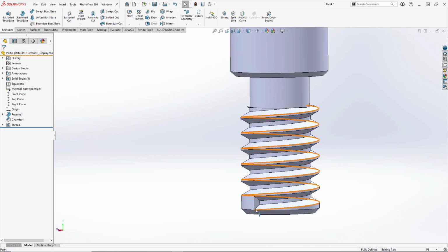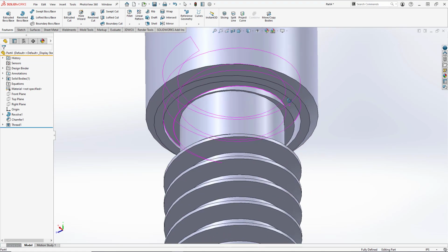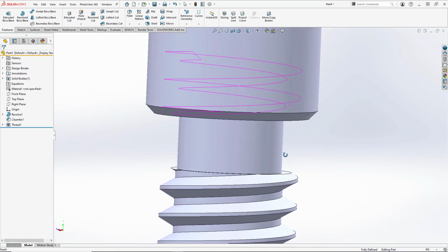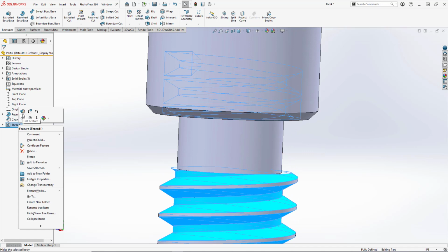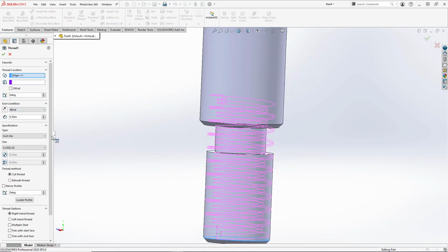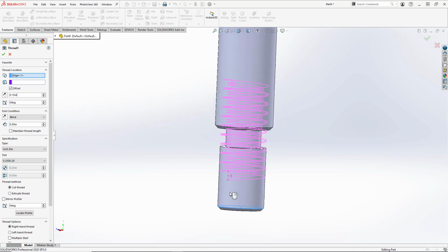You see we have this awkward stop point, and also it starts cutting into the shoulder portion of our bolt. We don't want either of those things to happen. So we'll right click and go to Edit Feature, and we're going to select Offset here, and we'll set our offset to be 0.15 inches. Let's see, it's going in the incorrect direction. It's going upwards and we want to go down, so we'll simply hit reverse direction.